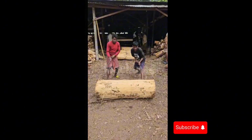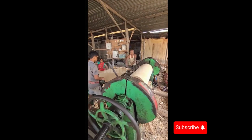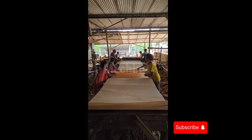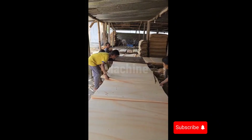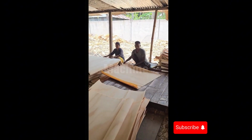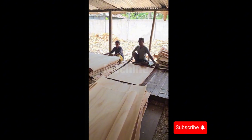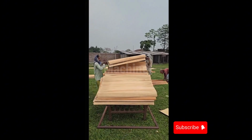The wood is cut into logs, debarked, and damaged parts removed. The wood is then fed into a sawmill to create thin layers. The wood slices are fed into a drying oven to remove moisture, giving the plywood high durability and preventing warping and termites. The drying process is strictly controlled to ensure that the wood reaches the standard moisture content.